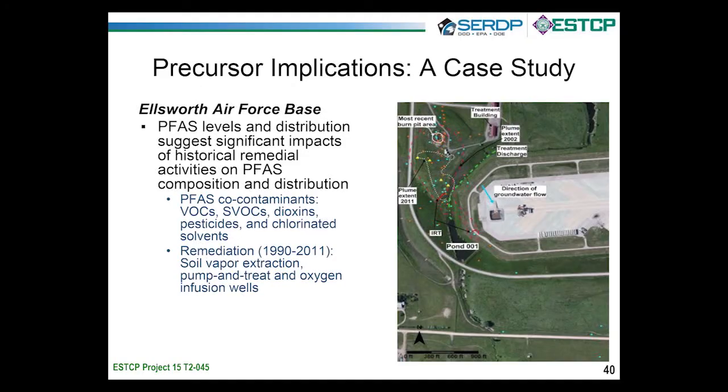PFAS was introduced through AFFF use at that site decades ago. Remediation started in 1990 to target co-contaminants like VOCs, SVOCs, dioxins, pesticides, and chlorinated solvents. Remediation happened for over 2 decades. Remedial activities demonstrated at that site include soil vapor extraction, pump and treat, and oxygen infusion wells.